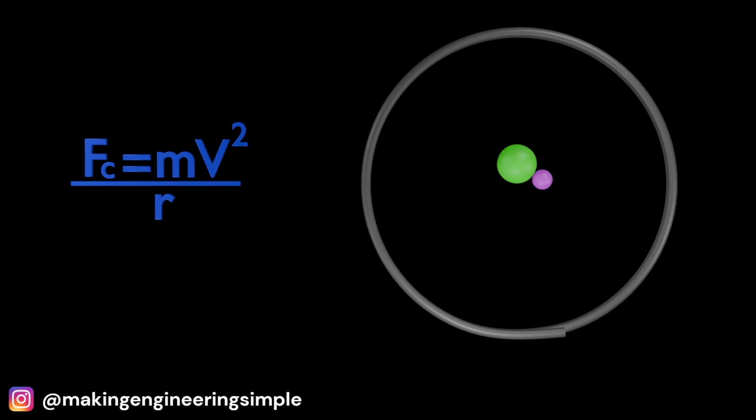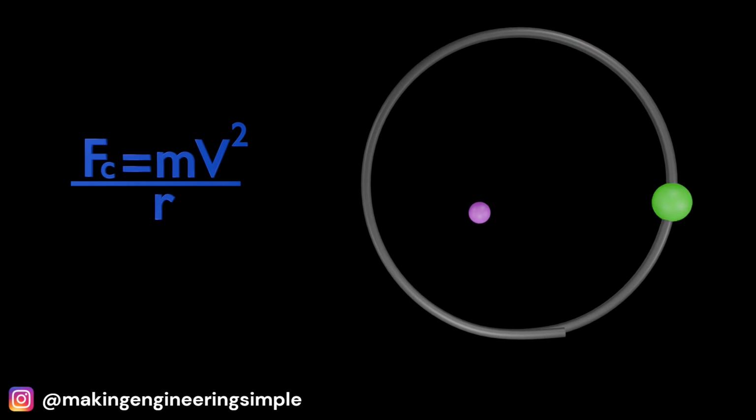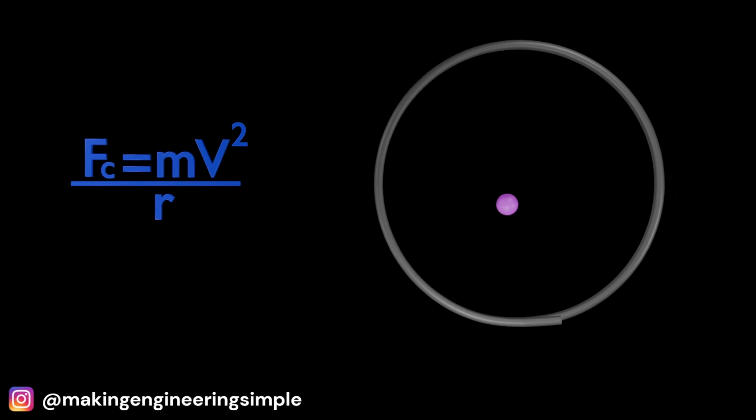Let's look at an example. As the gas spirals, the centrifugal force pushes particles toward the outer wall. Watch the large particles, they have more mass, so they feel that force immediately and get flung to the edge with a larger radius cyclone. Once they hit the wall, friction takes over. They lose velocity, slow down, and gravity pulls them down the cone into the hopper.